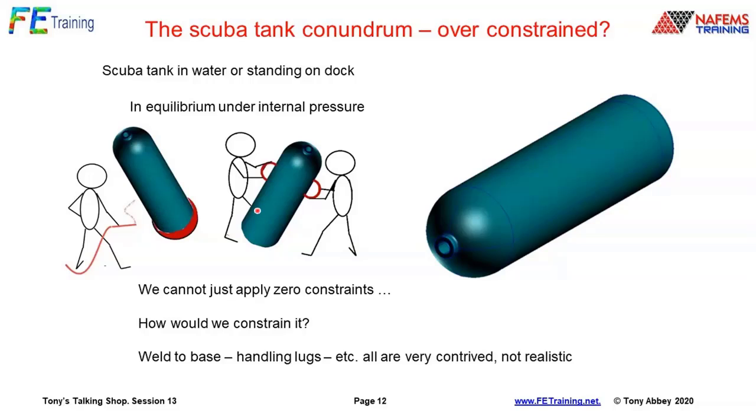These guys are trying to put some sort of handle on it to say, well, we can constrain it. In the aircraft industry, we used to call these sky hooks. Something comes down from the sky, tries to grab hold of the aircraft structure and stops it moving around with rigid body motions. Anytime I do that, I'm going to put local stress disturbances on. So the constraints are disturbing the natural balance of that.